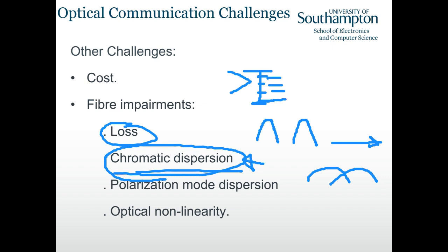However, in wireless communication, we have a similar dispersion effect. We have a transmitter, we have a receiver, we have a line of sight, and we have a lot of reflections. So this is multi-path. Each path would have different delays and phase rotation. They arrive at the receiver, sometimes adding together constructively, sometimes adding together destructively.